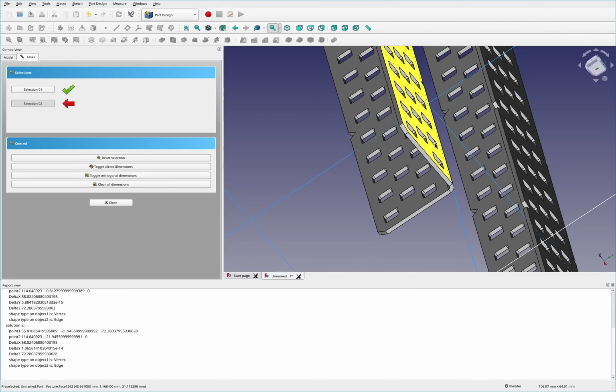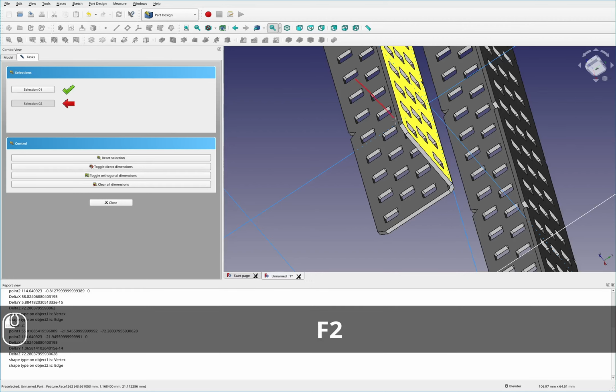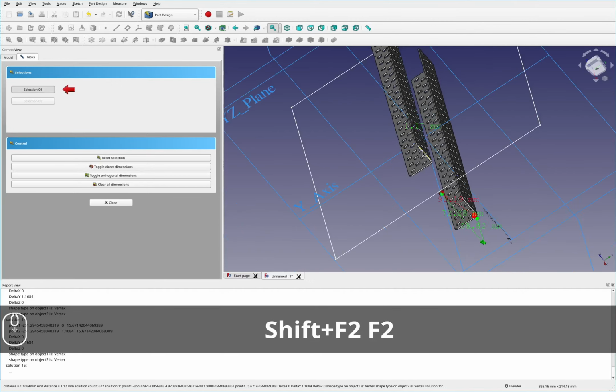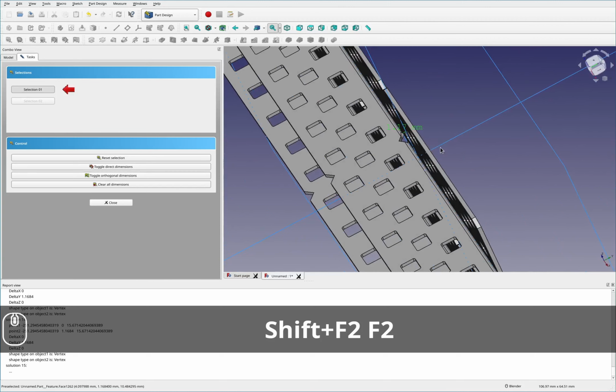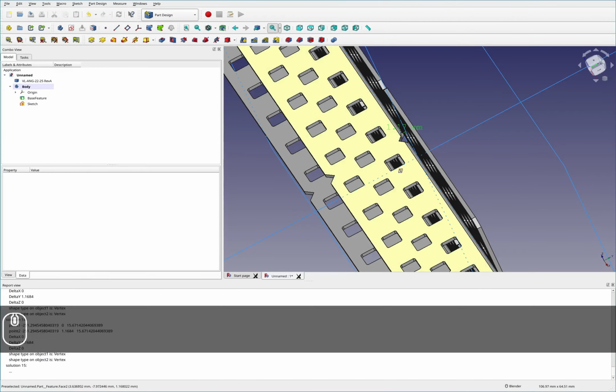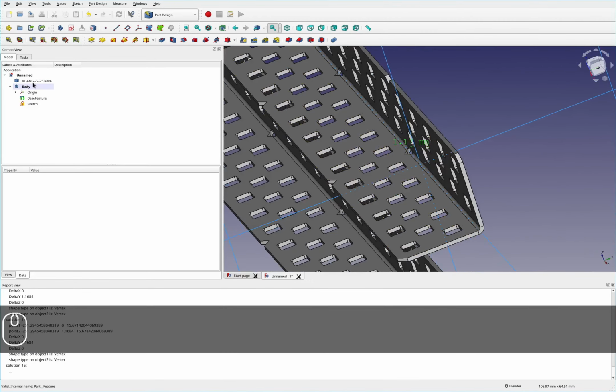And it is thinking. It's probably going to have a big think because it's going to be comparing the thickness of all of these holes and everything to find the smallest thickness, and that is probably not great. I guess what I should have done is measured from this particular point to that particular point, but that's just a limitation of this particular section of FreeCAD. And we've got 1.17 millimeters, and I recognize that as kind of a standard sheet metal thickness.